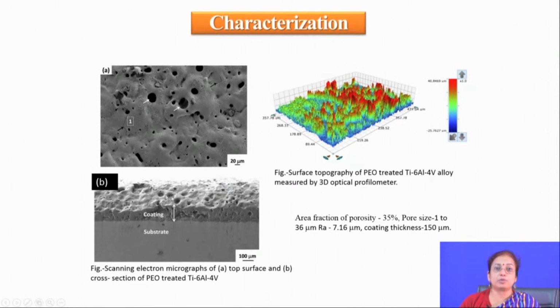So, even though there are porosities on the surface, these are not interconnected, mainly because whenever there is channel formation, there is porosity, but the channel is closed again because of the molten metal flow from below the oxide region onto the surface. So, the intermediate portion, if you see, is full of molten metal, but in the outer part there are a lot of oxides which are closed in nature.